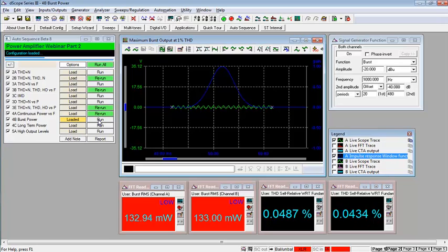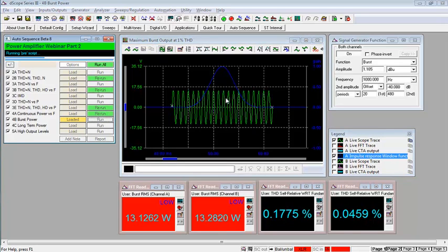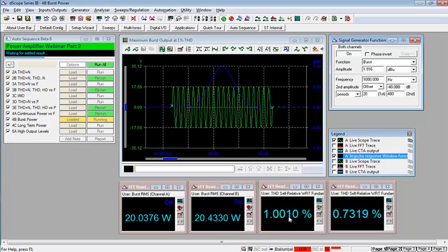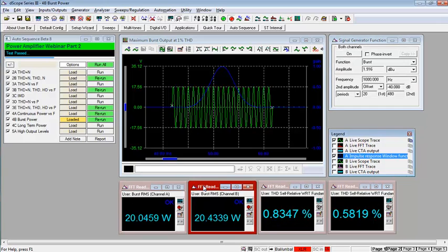So now when I run this test, you will see the waveform here is being adjusted up and down incrementally. The harmonic distortion has now breached the 1% limit, so we've got to ramp back down slightly. You can see the levels changing up here in the signal generator as we're seeking out the 1% total harmonic distortion point, and that has now been found,